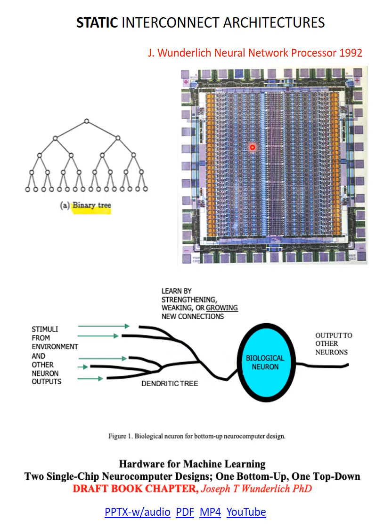There's 64 neurons here. This is analog, with capacitors, as well as digital on here, and a big decoder down the middle, and then memory elements, registers. We clock in 4-bit values for the duration of the impulse into each of the 64 neurons.